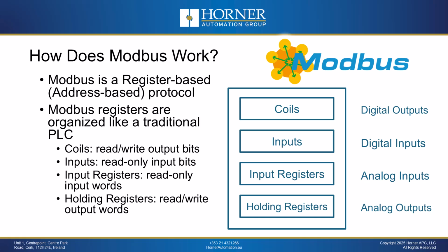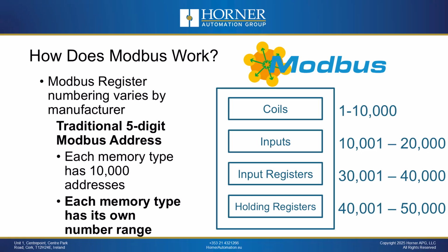A lot of drives, such as the Invertec drive we will use in our demonstration, are primarily based on holding registers from a Modbus perspective, so any data we need to read or write in this case is mapped to holding registers. How these registers are numbered will vary depending on the manufacturer.